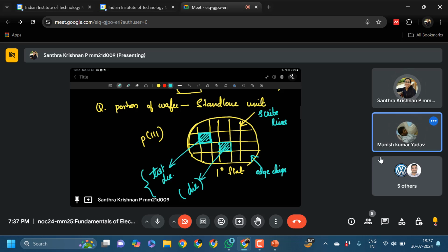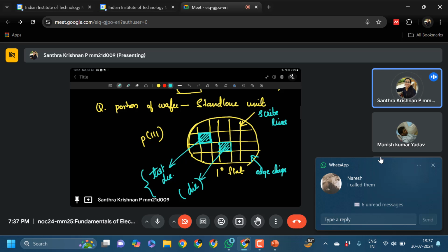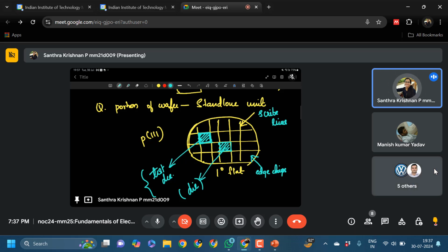The thing is, there are many of them, right? If we take n number of dice and test them, and assume all the dice will work fine just by testing a single one, or one thing is we cannot test all of them. It will be a very time consuming process. Even here we are talking about a single wafer, but when we are manufacturing in bulk, testing each die won't be possible. So we take a wafer from the lot, test a few dice in them, the test dice, and if that test goes beyond a particular level of quality, we assume that the entire wafer is working well. Testing every die on every wafer is not practically possible, right?